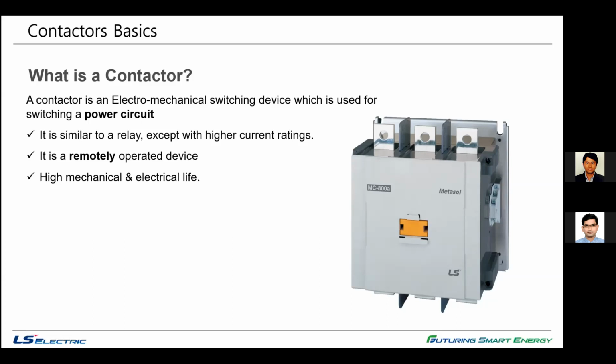Just to understand more, it has a high mechanical and electrical life. Do you know how many times it operates per hour? It's 1,800 times in 1 hour. And what is the durability, the mechanical operation? It is 15 million. That's too many times, frequently making on and off. So this gives us more idea about the contactors.